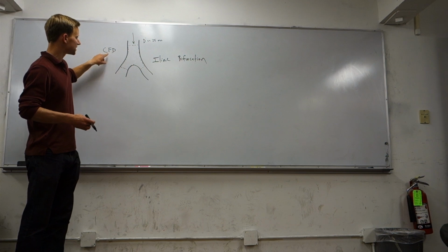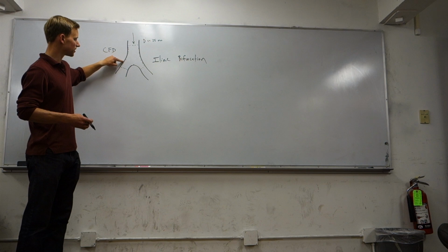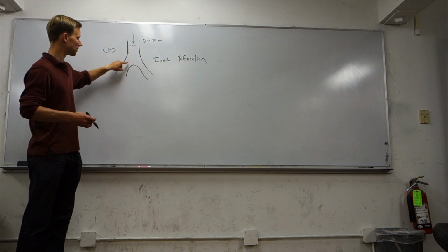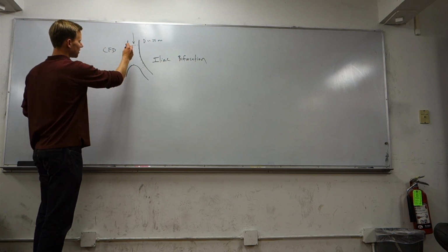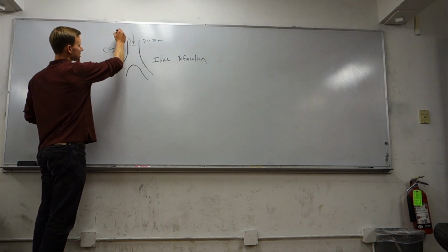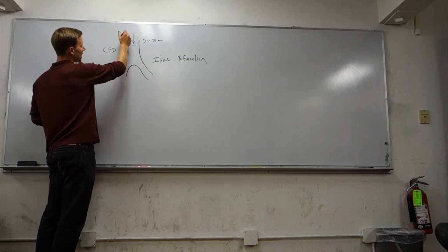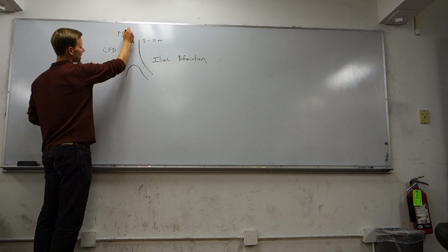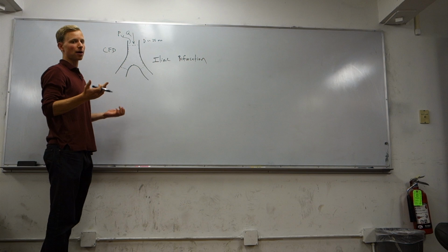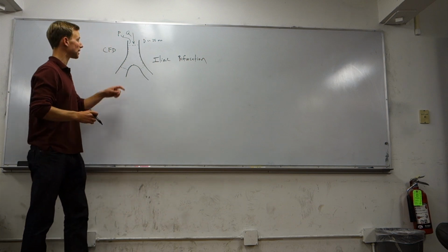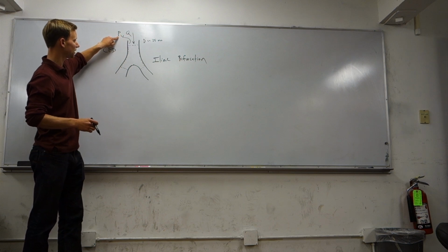So in order to solve CFD, we still need to understand the boundary conditions on all surfaces of this region. We can use the no-slip condition maybe on these walls. We need to know what the boundary conditions are upstream and downstream. So the problem at hand that we have today is we want to understand what the inlet pressure will be at this boundary condition. And this might seem contrived. However, we could actually back this out by measuring a volumetric flow rate, a Q, at this region. And Q can be measured using MRI, phase contrast MRI, which gives you an experimental knowledge of what Q might be. And then knowing Q, we wish to find P.